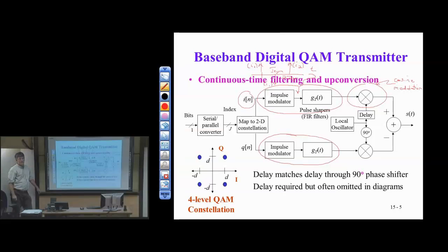All right. The second channel of QAM, well, I'm also going to have another baseband PAM step: impulse modulation followed by pulse shaping. I have another constellation map set, for PAM. It's a separate PAM signal, if you will. And then I'm going to upconvert with the sine. So here's sine modulation. And I just have to make sure that these two are 90 degrees out of phase.